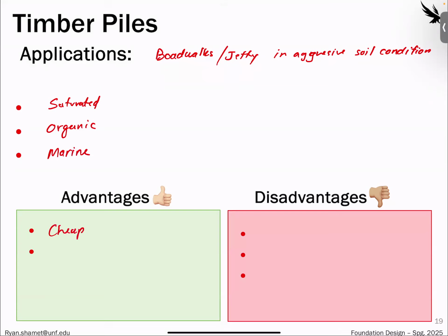So that's why I want to include this in here. If you're working on a project for a private client or something, then this might be a good option for low structural loading. Although DOT and federal stuff, federal highway, they don't even have standards for timber piles, it is still an option to achieve the goal in consulting. And also very long life if you use the right wood. So if you're using it in the right conditions, then it'll last super long.